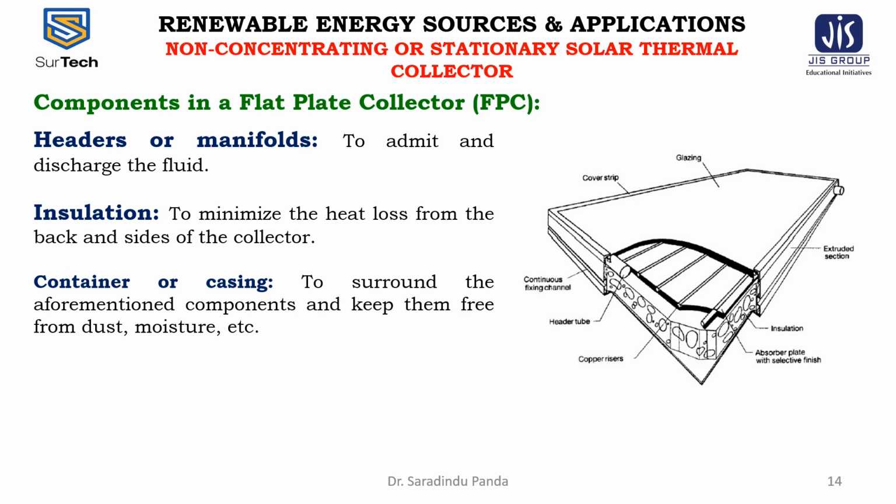This investigation used the polystyrene as insulation because it is cheap, easy to find, and most importantly the polystyrene has the good heat insulation characteristics. The materials most used for insulation are mineral wool, glass wool, and the foam glass. But wool can absorb the humidity from the atmosphere and the thermal insulation deteriorates substantially. So for this reason it should not be used. The polyurethane foam is used for low temperature applications and the styropor is used very rarely.